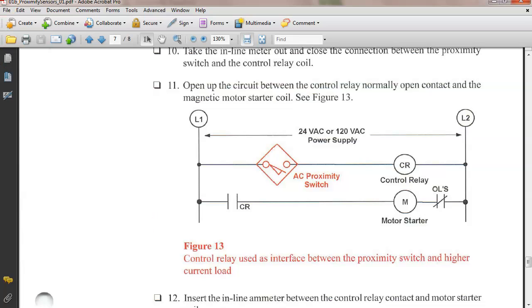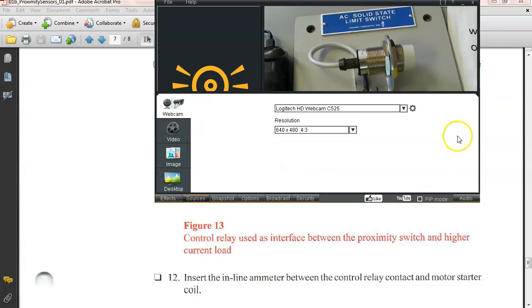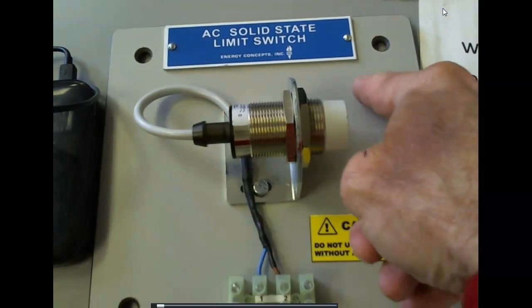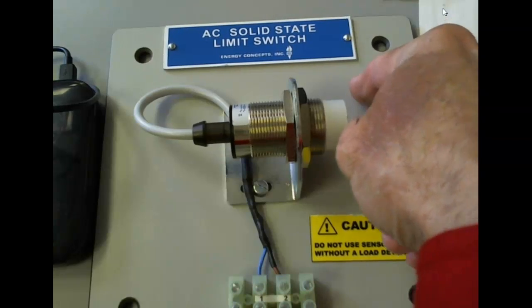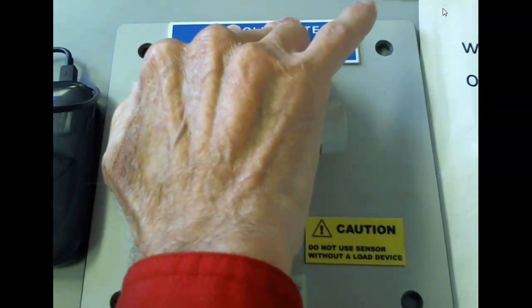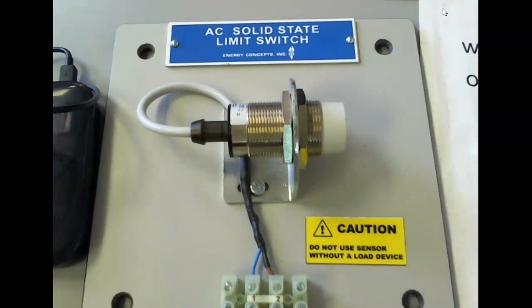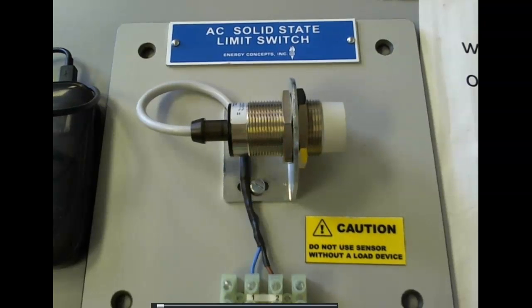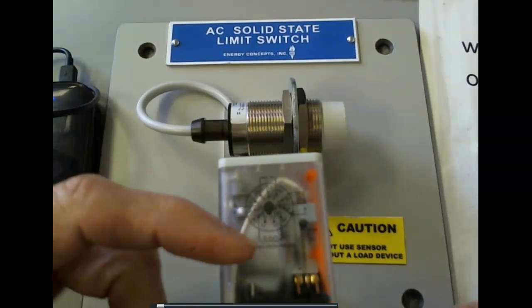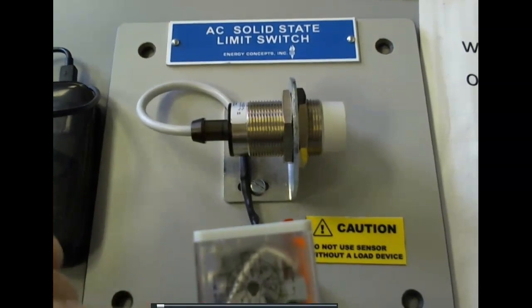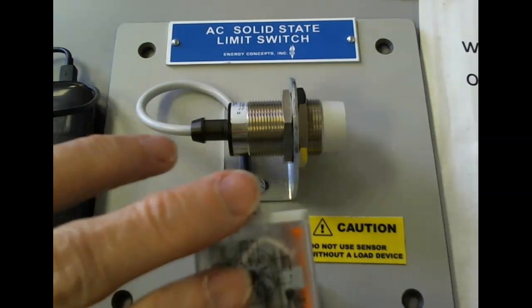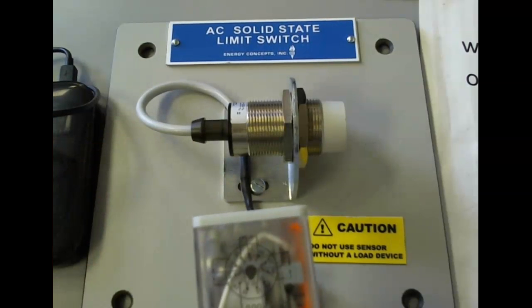So when you use these things, these are quite a bit different, guys, than motor controls, and we talked about this. Notice there's no little plate up here that shows you the pinout, right? Y'all understand that? So where are you going to look that information up at? In the data sheets or the little book that we have in there. A lot of times on your control relay, they'll have the symbols on the side, and then they'll show you the pinout also. So that's another thing you might start realizing, especially on little control relays. A lot of times they'll have the actual pinout on the relay itself.